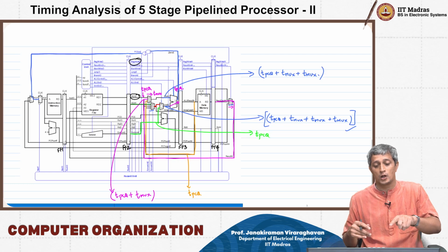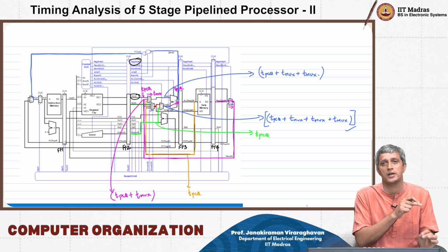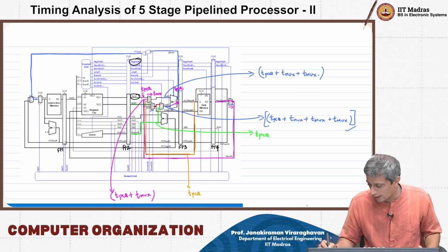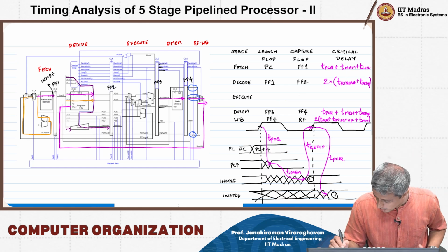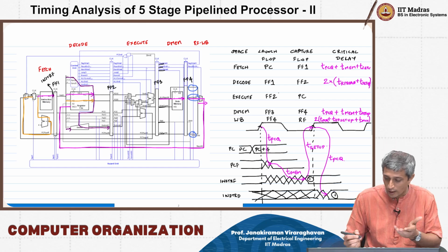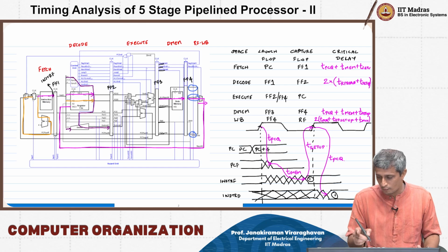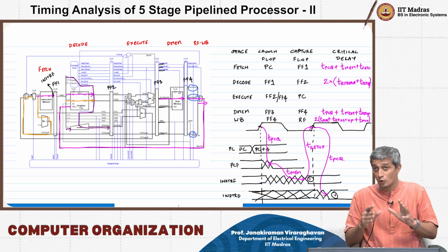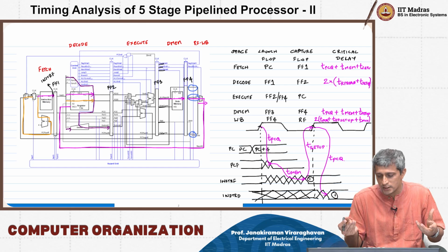However, you also have an additional AND OR logic plus one more multiplexer delay, and the capture flop therefore now happens to be the program counter, okay? And this is obviously going to launch from FF2, right? Or FF3 actually, FF4, I'm sorry. It could come from FF4 also. So if you look at the capture, the critical path, who is launching this data?